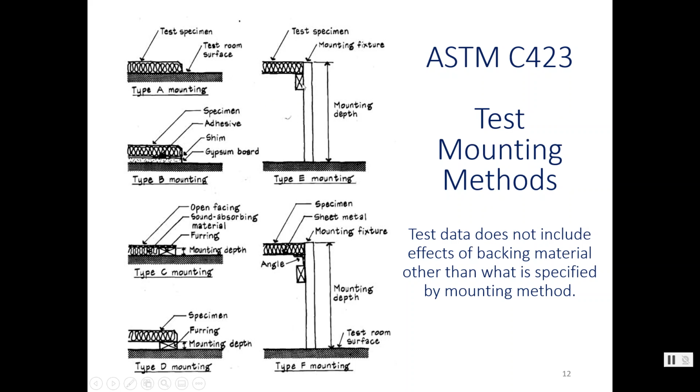So know when you get, say, an acoustical ceiling tile and you get the absorption coefficients for it, it's likely tested in this E400 mounting. If you instead took it and mounted it A-mounted, say there's a gypsum board ceiling and you just want to come in and apply it to the underside of that, you're not going to get nearly the absorption that you get here with this big gap behind.